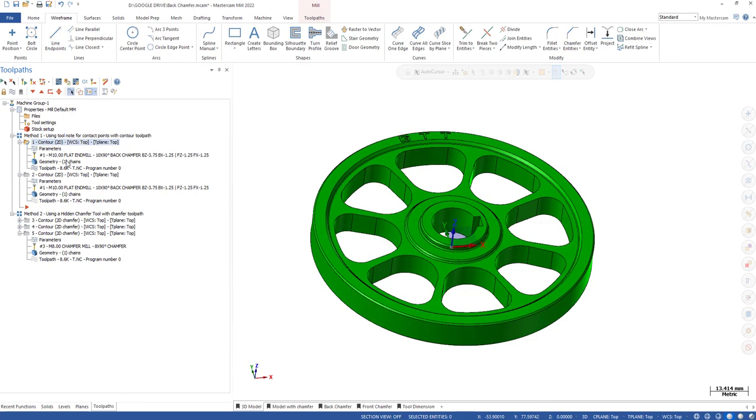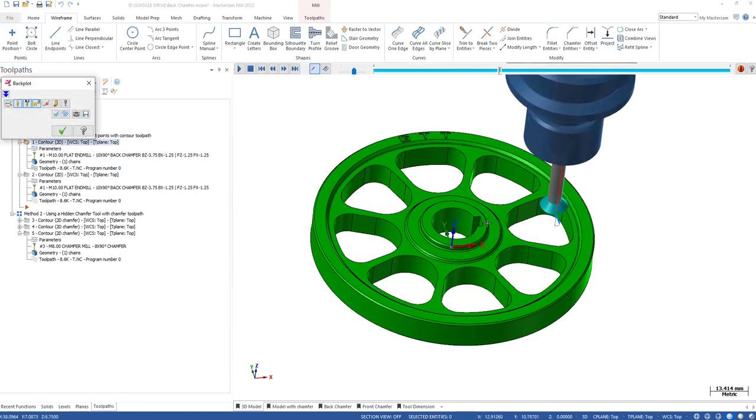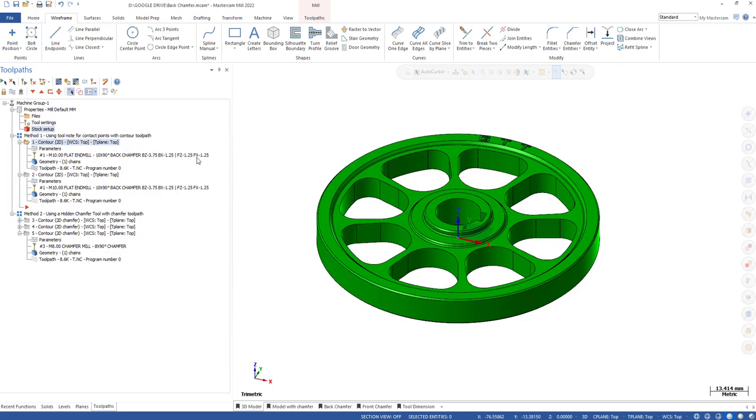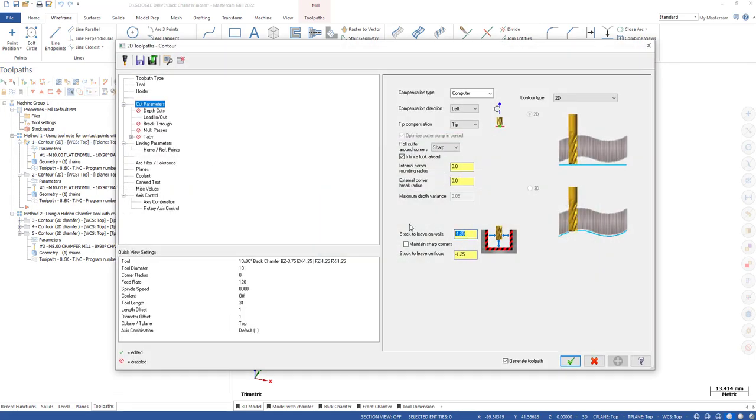So in the first toolpath I do a front chamfer on the top, so I know what number can be used. That is the front Z, FZ, and the front X, FX here. I just input those numbers into this field: minus 1.25 millimeter for both X and Z, and then I move the tool to the correct position for the toolpath. It's quite simple, right? So where does the number come from? Quite easy. If you are used to working with this tool, you're gonna know how to take those numbers.